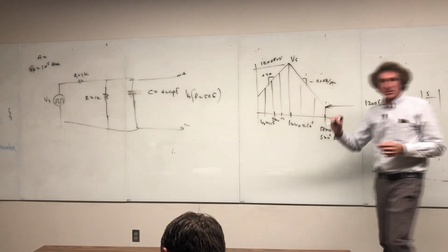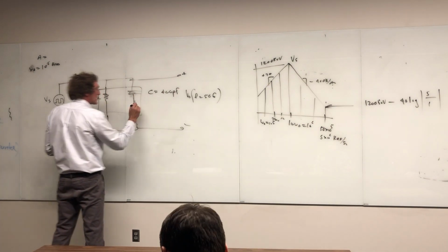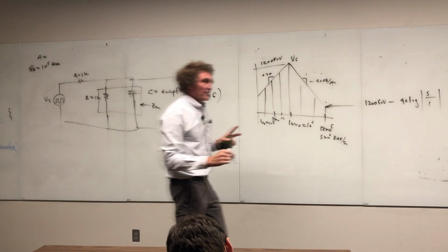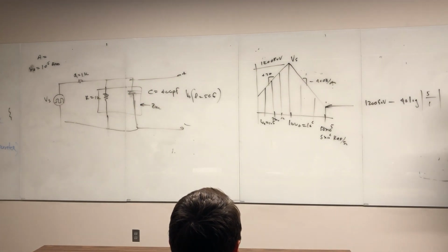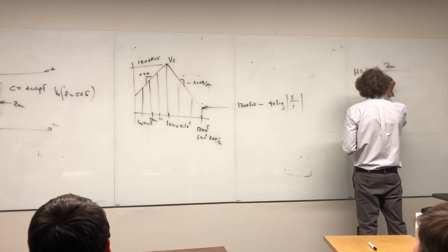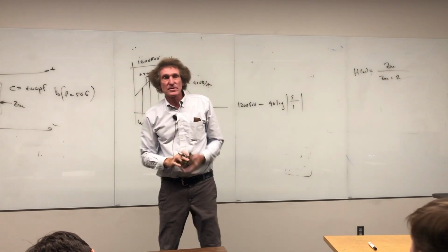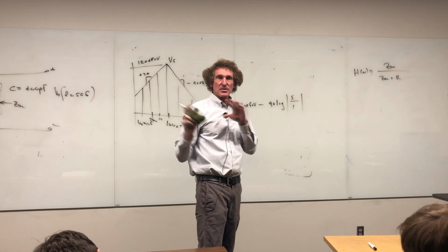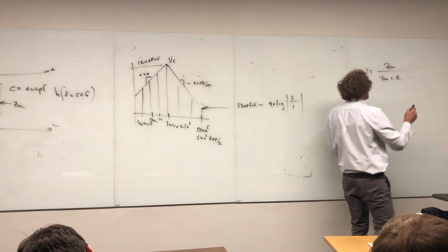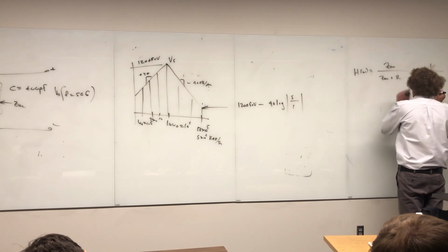Now, when you look at that filter here, this is the way I tell people to do it. This has a characteristic impedance. I can call this ZRC. Are you with me? Now I can say that my filter here, H of omega, is really equal to ZRC over ZRC plus R. If you take a look at that, the only thing I've done is eliminated the 1 over j omega c and the R thing in parallel. So I just simplify it, right? Now I divide by that impedance, ZRC, and I get 1 over 1 plus R divided by ZRC.